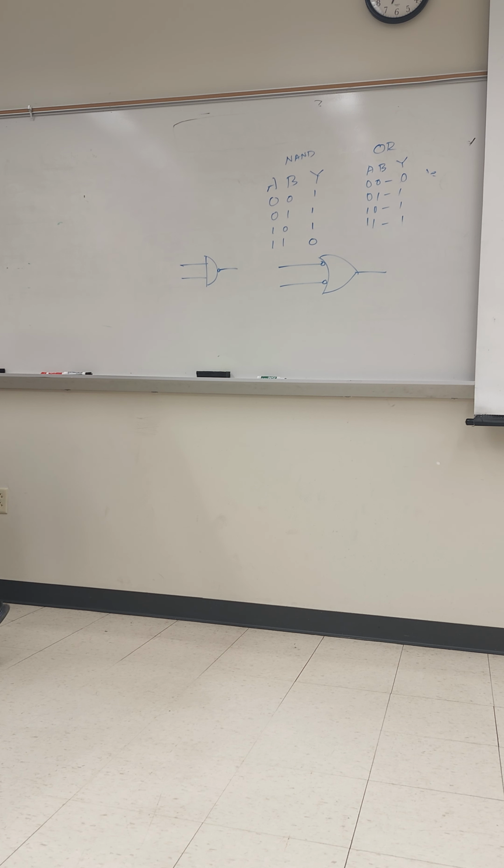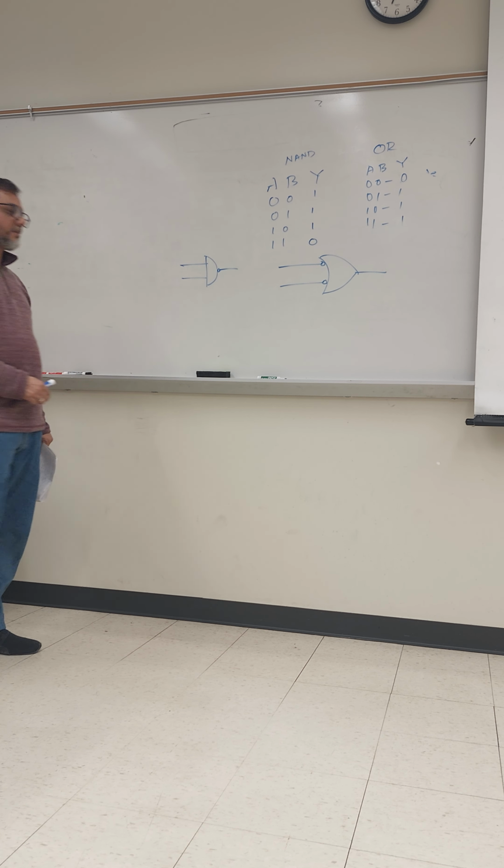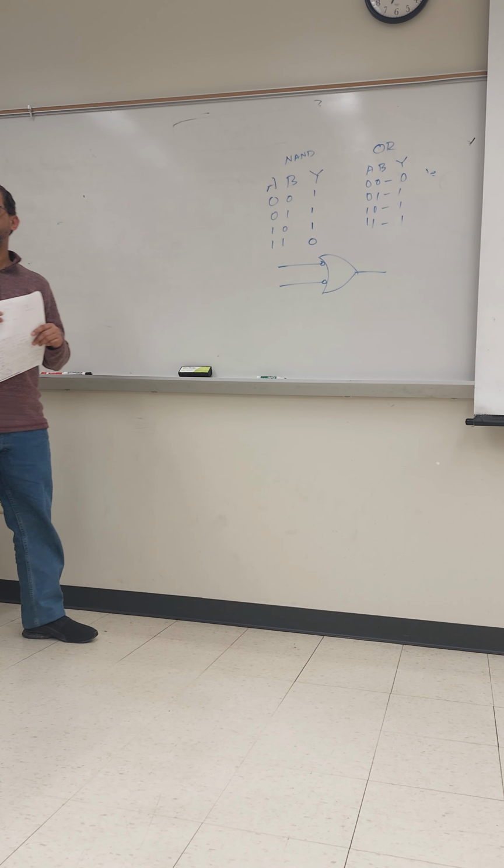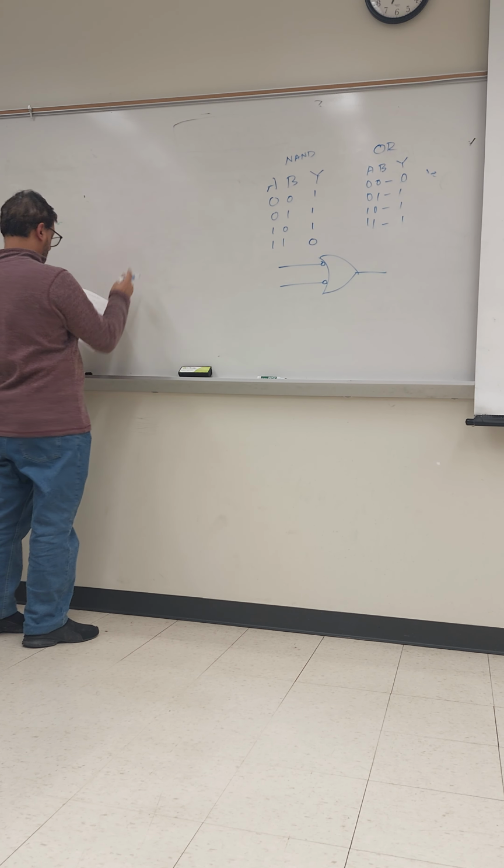When the volume of chemical in a tank drops to 1/4 full, the sensor puts out a low level of 0 volt. It is required that a single green LED on an indicator panel show when both tanks are more than 1/4 full. Implement this function using a NAND gate. So you have to understand and just draw the circuit. In a manufacturing plant, we have 2 different kinds of chemicals, so we have a tank for each of the 2 different chemicals.